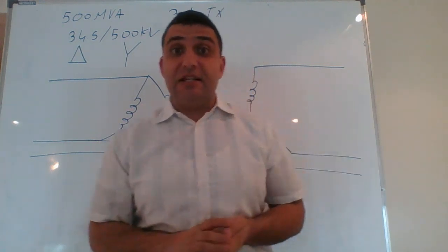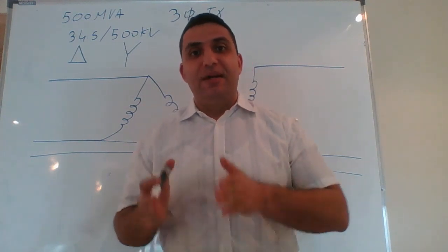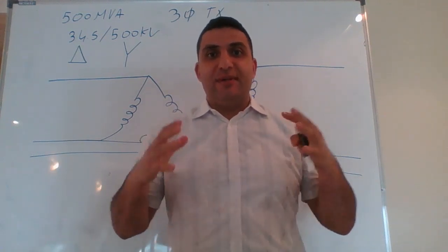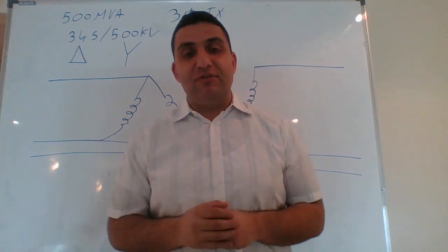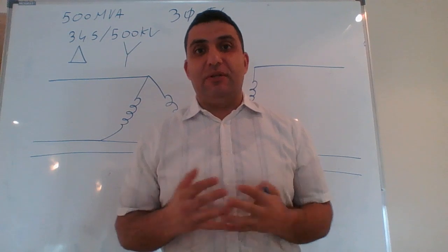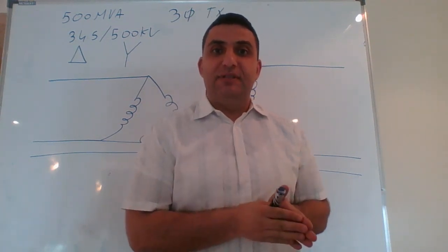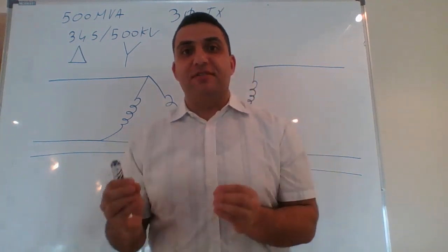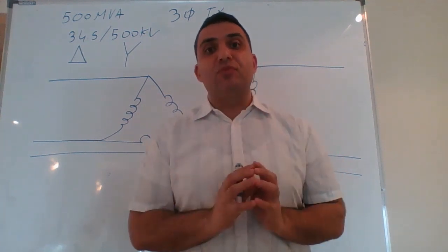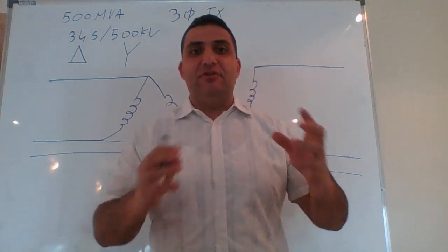And then last lecture, we started the percentage differential relay design for a single phase transformer. We explained the concept behind the percentage differential relay for a single phase transformer. We showed the circuit analysis and we did an example as well. Please refer to the previous material for a quick revision, because the concept of differential protection is exactly the same for three-phase and single phase.